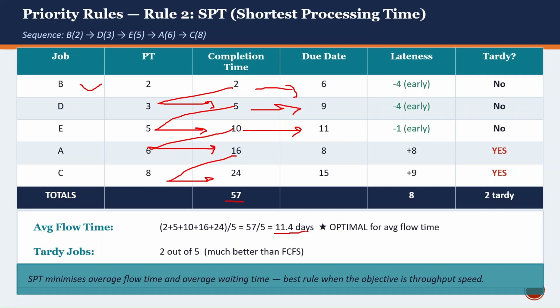This is the base rule when your objective is to achieve the maximum amount of production, or we want maximum utilization of the factory. In that case, I can use the SPT rule, the shortest processing time first. But sometimes some products will have an early due date, and the demand for that particular product may be larger. For that case, we need to go ahead with the earliest due date rule.